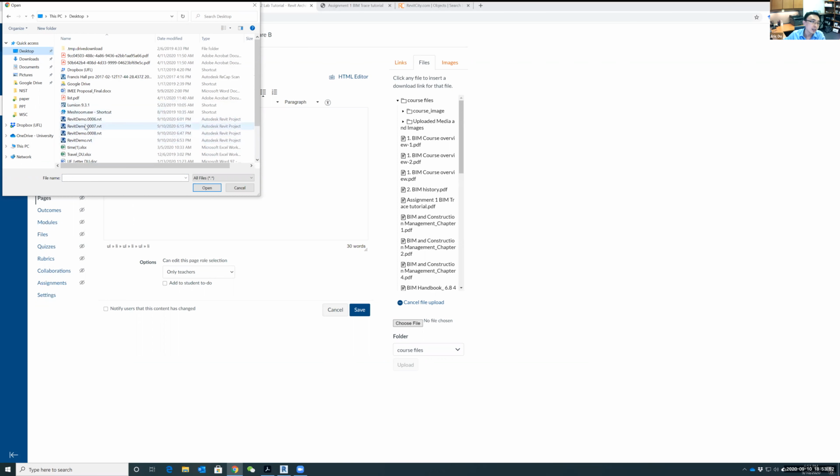So this is what I said. Revit will create a lot of numbered files. That's the working process model. Don't save them. Save the one without a number.